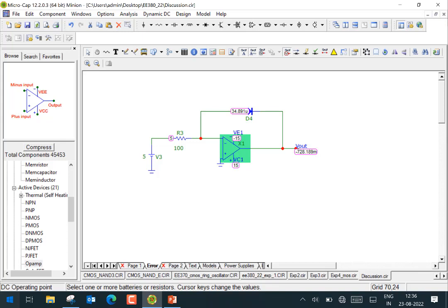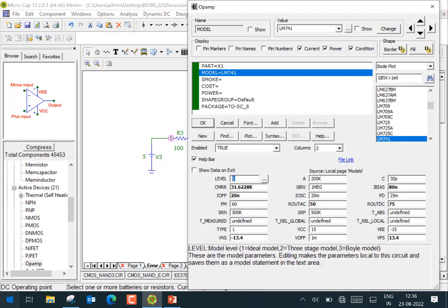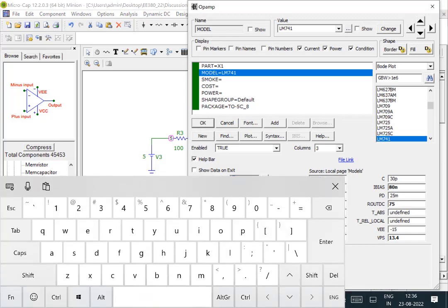So this is what was happening. The lesson from here is that every op-amp has a current limitation. If you try to force more current than it can handle, then all these problems are likely to occur. So that's something to be aware of. Now, these things can occur in many different ways. For example, let me go back and make it a practical op-amp here.